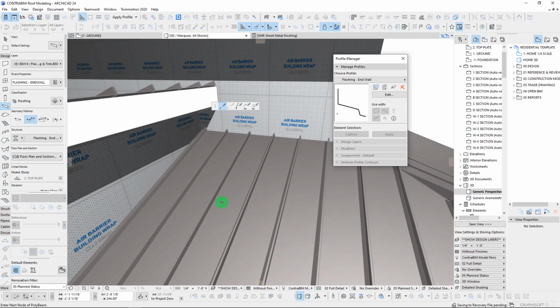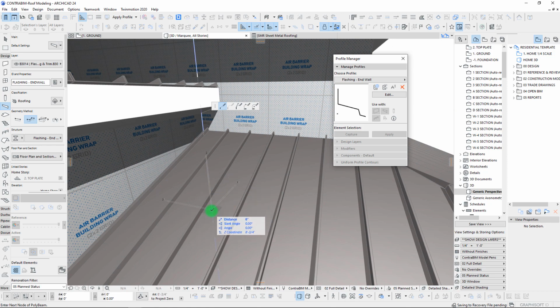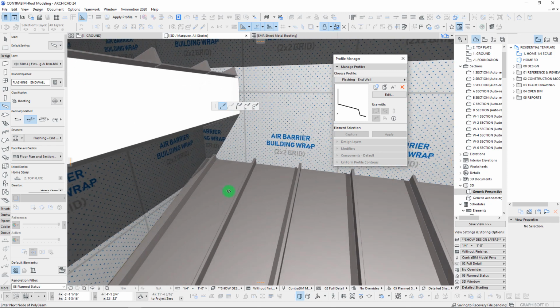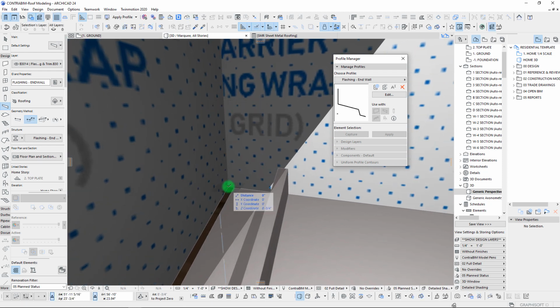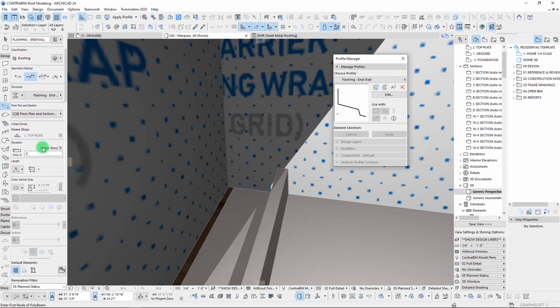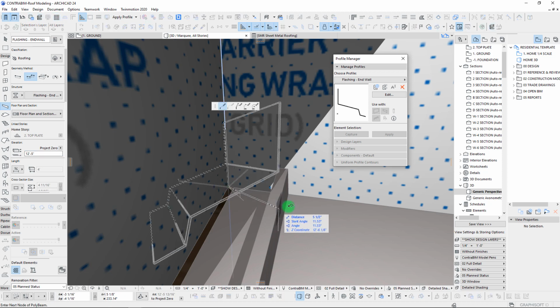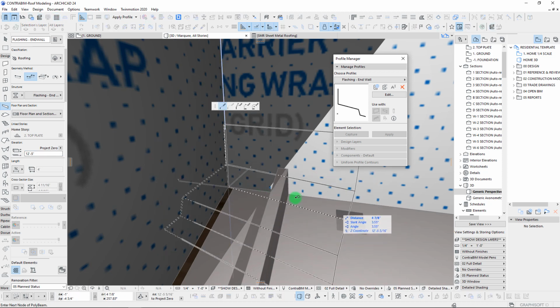Now you'll notice with this beam, it's set down here to our base point from our home story, which in this case is the top plate. If we wanted it to start right from this point over here, we could measure, and then just pick up that Z coordinate, which is 12'5", and so that's going to get us close. So in this case, we can set this to project 0, 12'5", and so that will become our new base point for our beam.